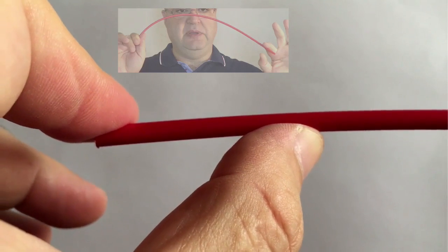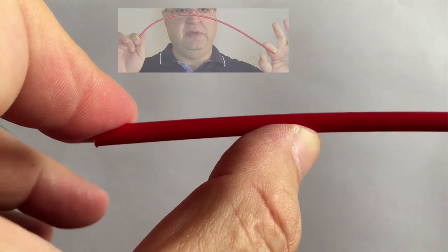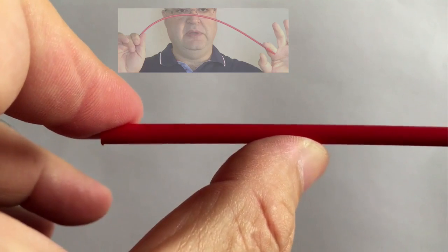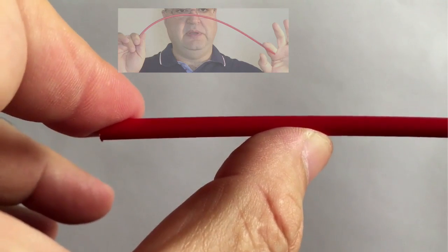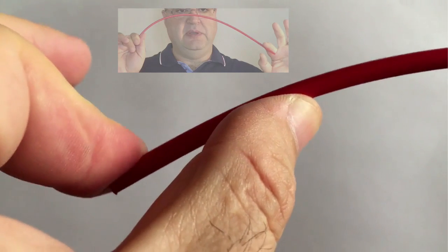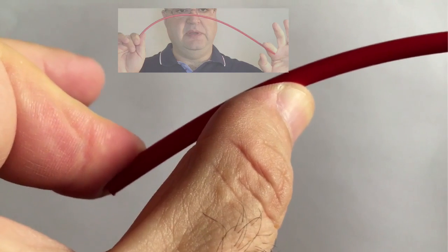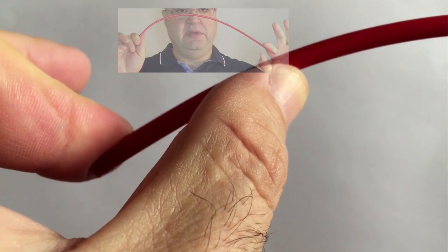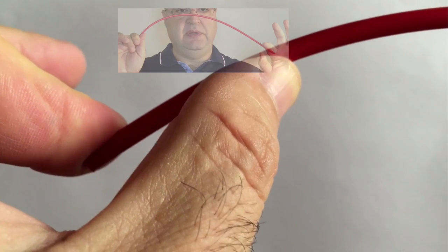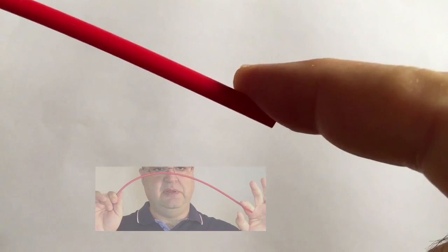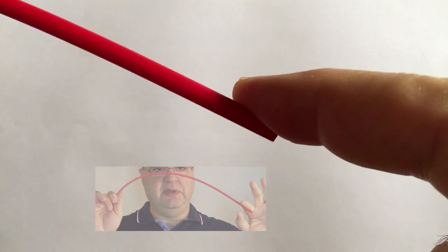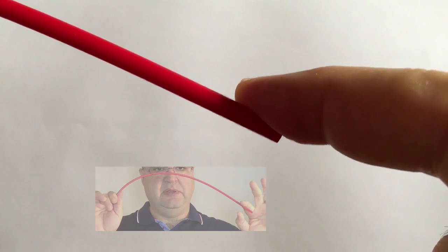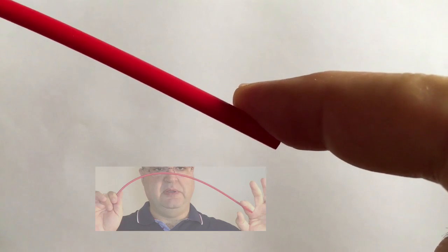To apply the bending moment, I'm actually applying two forces that are separated by a short distance. The two forces are not equal, and my thumb is applying a force up more than my index finger is applying a force down. So there is a net force up and a net applied moment. The net force up simulates the effect of the left hinge. On the other side, I apply a single force down sufficient to keep the beam horizontal. This force down would be provided by the hinge on the right side.